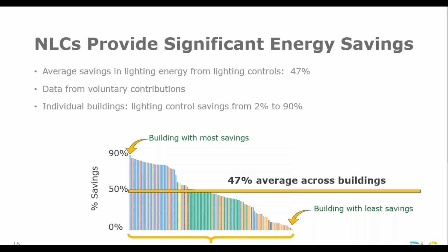The main take-home point for efficiency programs and others is that at this point, you probably need to base your lighting controls program design or your customer savings estimates on a portfolio average of energy savings across all the participating buildings. It'll take some more research to develop better predictions of energy savings at the individual building level.